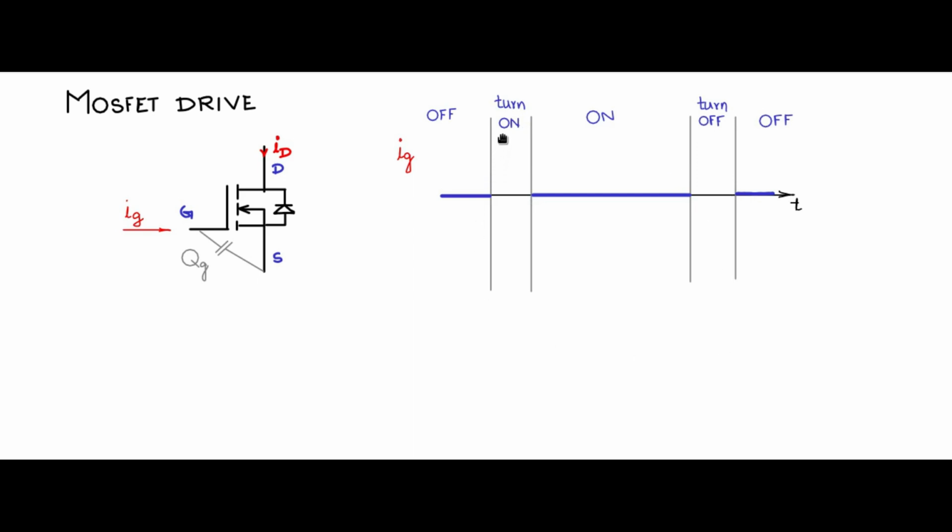So during the turn on period, you want to switch on the MOSFET. You supply a specific amount of charge called QG as defined in the data sheet for that specific MOSFET. After you supply that charge, the MOSFET will turn on. So let us say I will supply a current with some profile like this. The area under that curve is the charge QG. Now if I have supplied this QG amount of charge to this MOSFET, then the MOSFET will turn on, the voltage across the MOSFET will be 0.